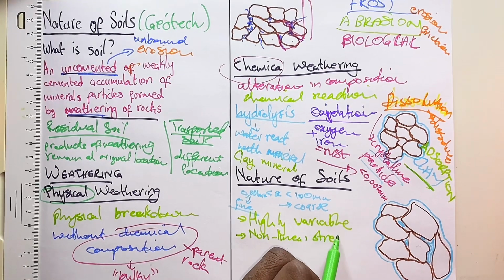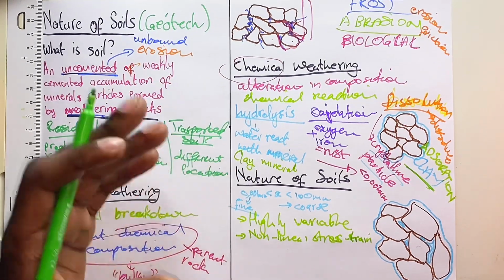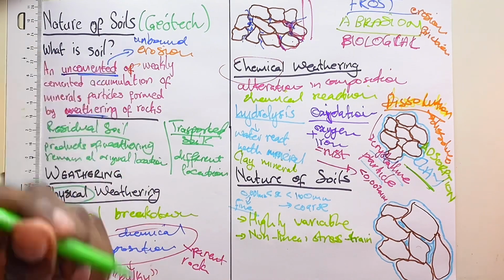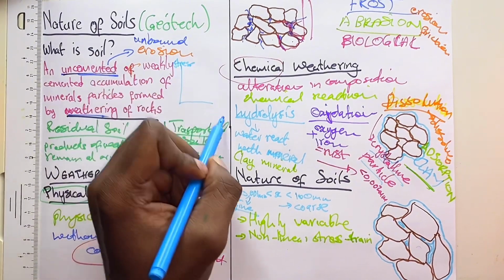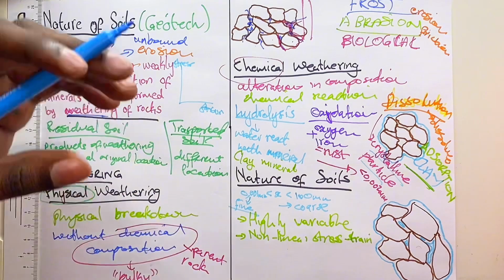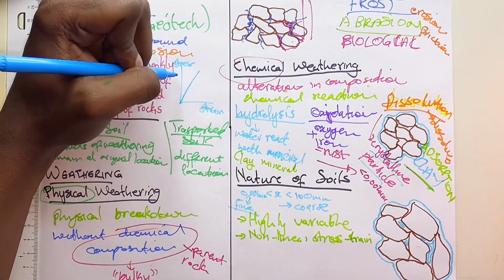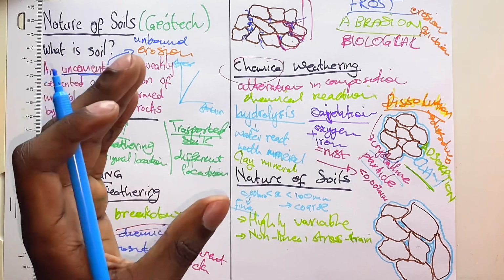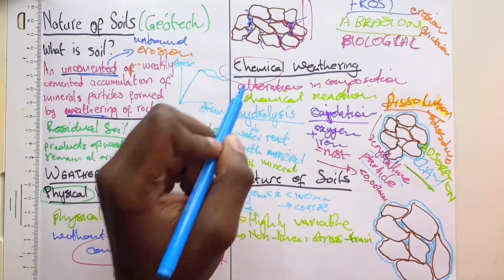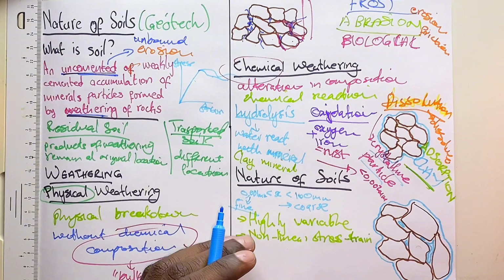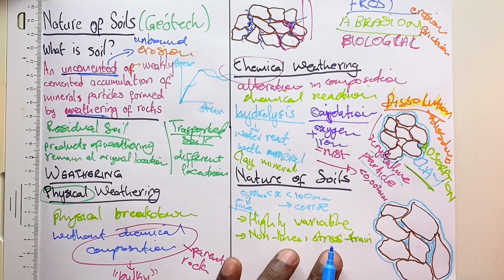Now also it does not have a linear stress-strain relation. When you have a material like steel, for example, when you draw the stress-strain response of a steel material, it begins as very linear, where the relationship between the stress and the strain produces a linear relationship before it becomes plastic. Now, with soil, it does not react that way. So your stress and strain response is very variable.